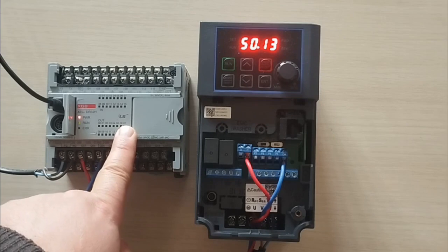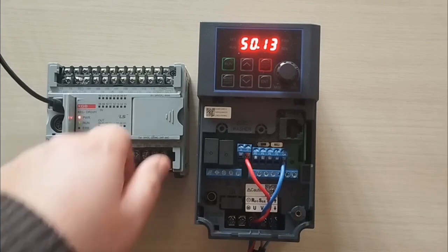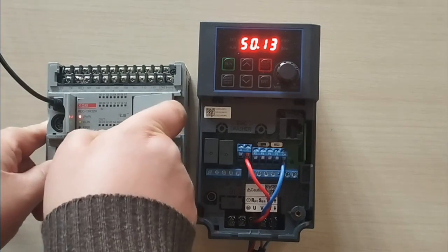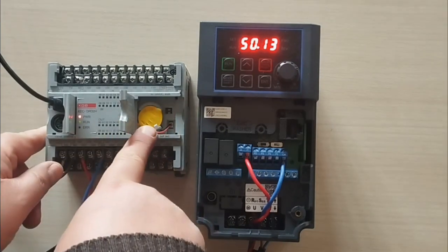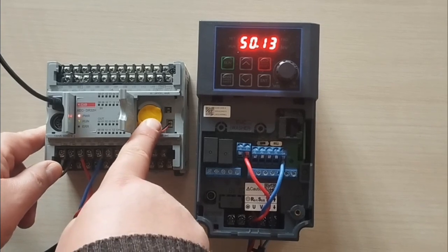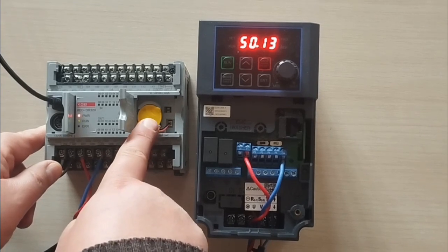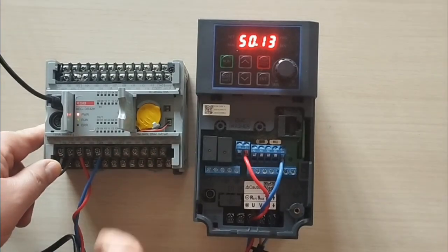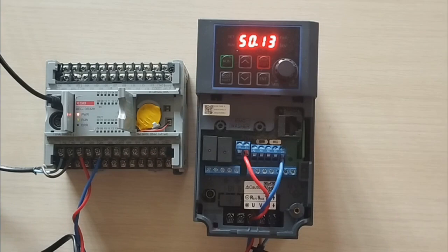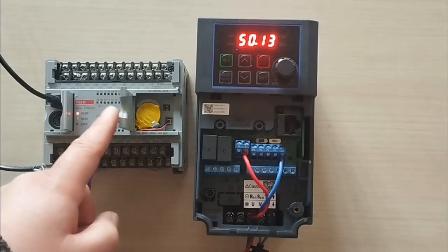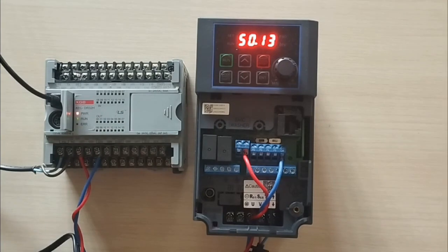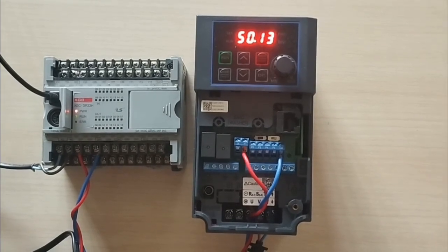This PLC model, the XEC-DR32H, is quite unique. If we remove this protective cover right here, you will clearly see that there is a dedicated battery located inside the PLC unit. So it is important to note that LS compact PLCs that have an internal battery include this feature, allowing us to set, maintain, and update the exact time and date on these PLCs for our automation tasks.